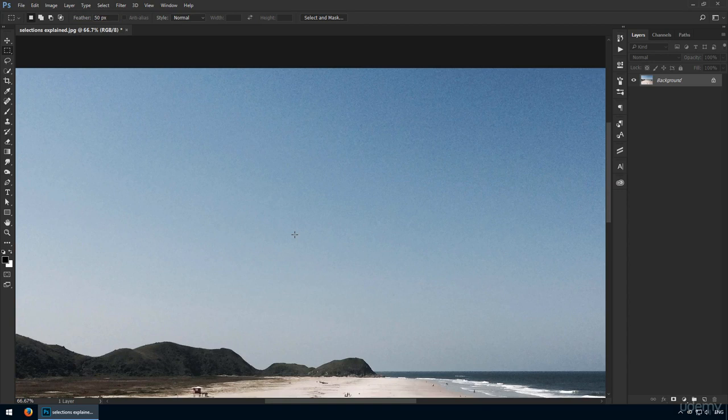If you repeat the process but you increase your surface area considerably, now Photoshop is able to fulfill both your selection command and the feather instruction. The thing is, once you set it, Photoshop will remember it even if you restart the program. You, on the other hand, might forget about it. So my advice is to always take it back down to 0 pixels.